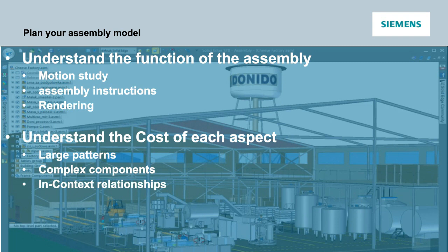If you have a highly detailed model of something, make sure that you also have a simplified version of that model as well that still has the pertinent information, but is not going to bog down the system with unnecessary edge displays or unnecessary complex faces. Maybe the simplified version is just a head showing the drive type and size of a particular bolt. Or if you purchase a driver cabin for a piece of construction equipment that you design, the detailed version of the cabin with all of the controls is nice for the rendering, but it may be completely overkill for the system assembly drawing.